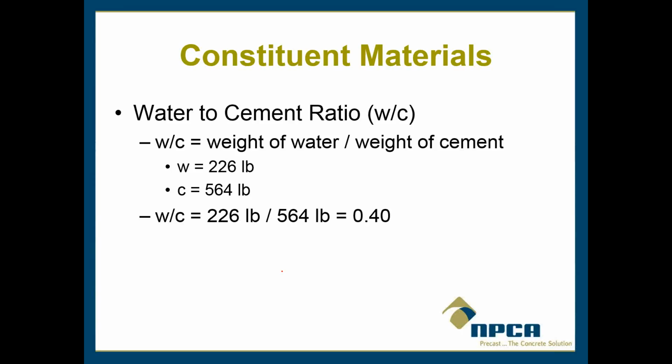So that's one of the millions of reasons why water to cement ratio is so important. If there's excess water, eventually it'll evaporate. It won't react. There won't be enough cement there to react. So when that water evaporates, it'll leave these air pockets, and it makes the concrete much more porous, and it acts like a sponge, and it just absorbs nasty things, chlorides, whatever else.